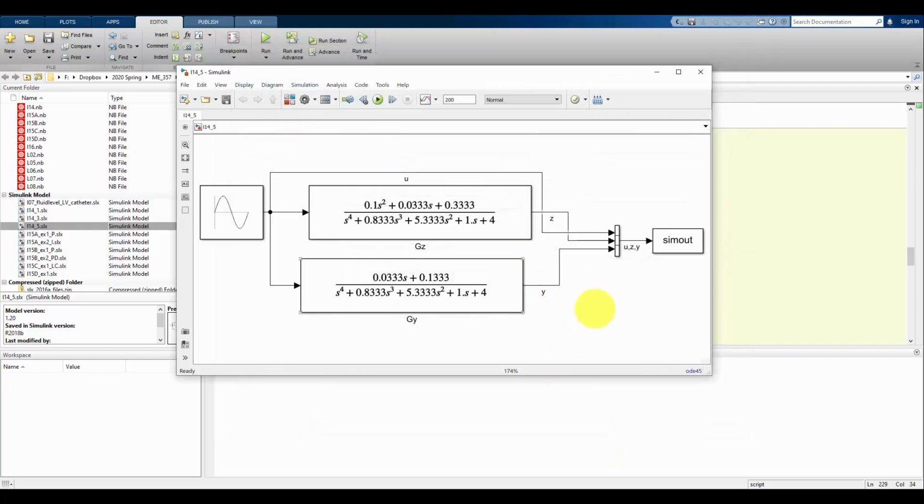And finally, I'm going to run this for 200 seconds. We're going to see that the transient phase is actually pretty long here. So you might run it for a shorter amount of time, see that you're not at steady state, and then increase what this number is. But we'll see in our results that 200 seconds will be long enough that we'll just enter the steady state in this example.